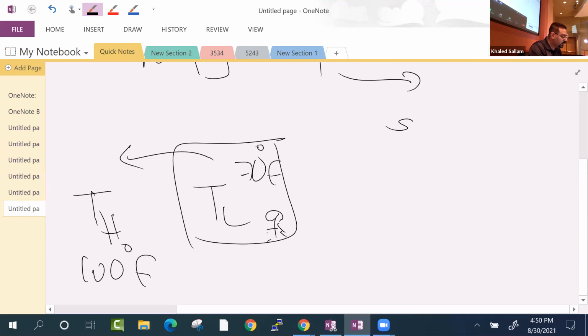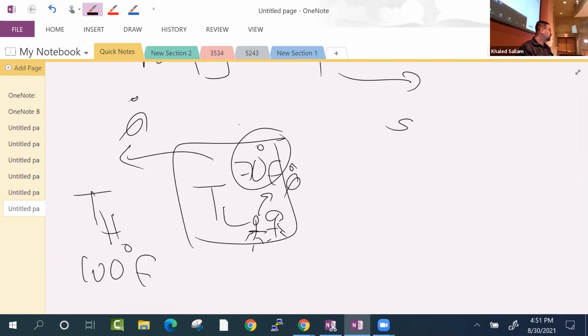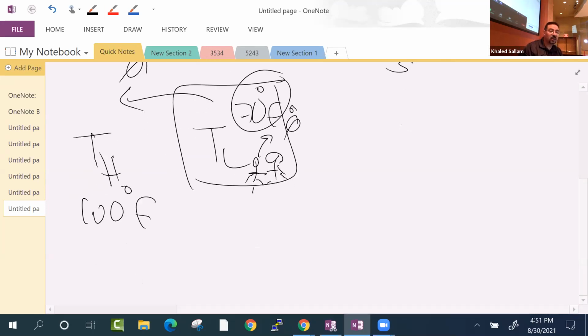Because the people in the classroom generate Q dot. Every one of us, our metabolism, is basically generating heat. And if we don't remove this Q dot, our 70 degrees will become 72, 73, 75. So we have to continuously move the heat, and we need to do it from T low to T high.